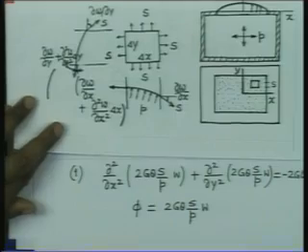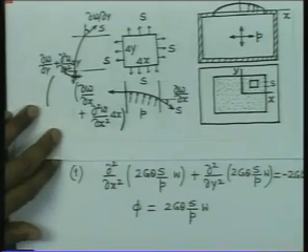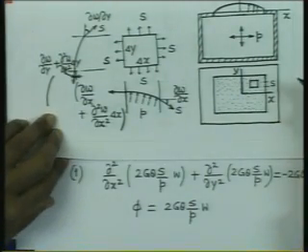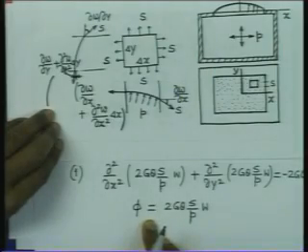By taking a membrane having boundary shape corresponding to that of a section one is interested in, it is possible to get the idea about the function phi, and hence one can calculate the stresses also.